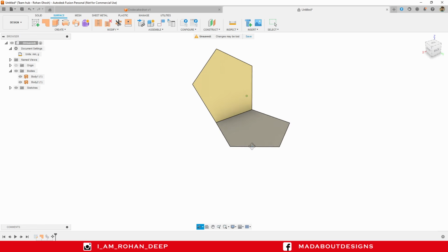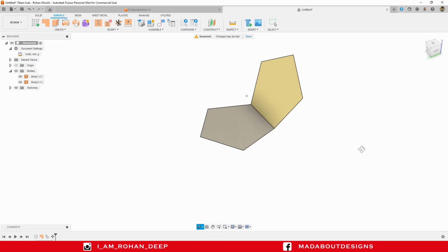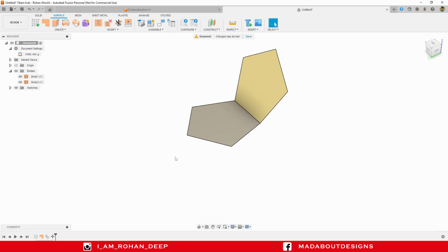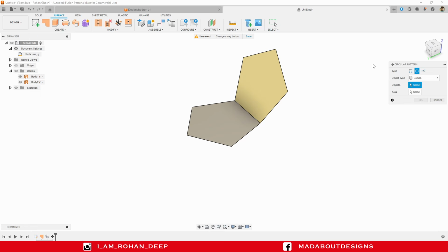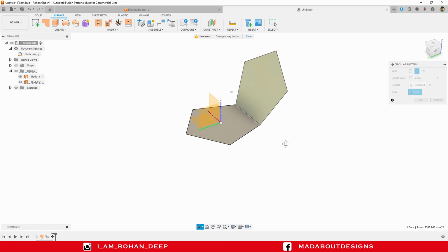Now I am going to pattern this surface around this shape. To do so, go to create pattern and circular pattern. Object type bodies. You can change it to faces also and select this surface. And for the axis, click on this blue axis.